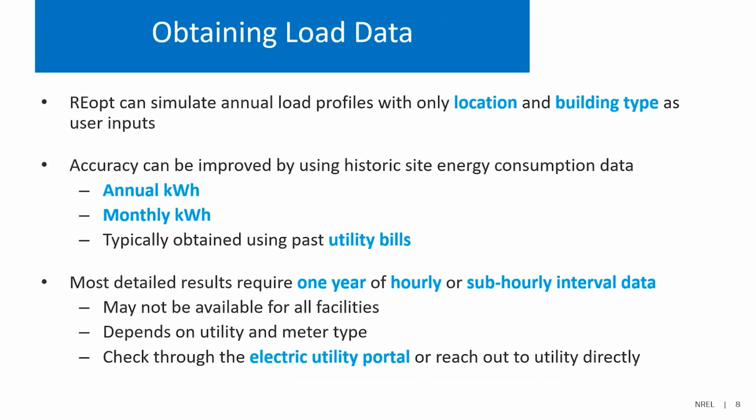Given this background of how important load profiles are for REopt, we are able to help sites at the different levels of analysis they're interested in, depending on what data they're able to obtain. At the most crude, high level, if a site is looking just to screen generally before down-selecting sites, REopt can simulate these annual load profiles with only two user inputs, which is just based on location and building type.